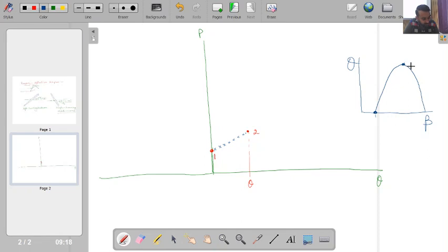Then if I once again decrease the theta, but now in the direction of the strong shock wave, the strength of the shock wave keeps on increasing more, but this portion is steeper, so here the number of points will be very less for the same value of theta. And then finally I will be getting nothing but a normal shock wave. So if I keep on increasing the value, which point is achieved? Theta max.